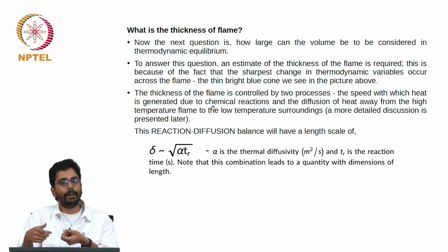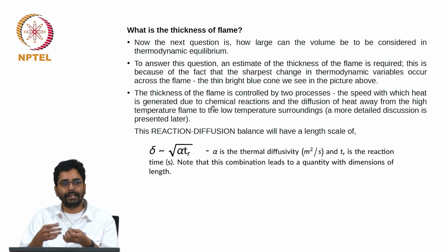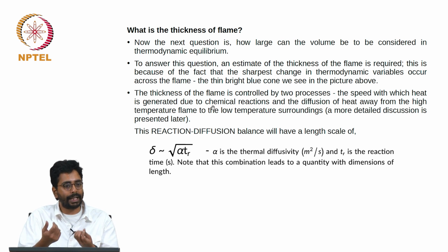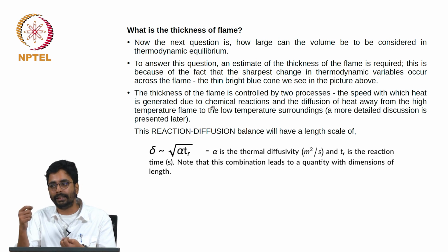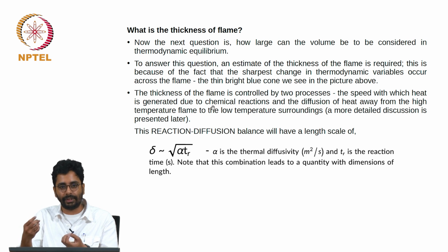time, but the reactants are continuously getting converted into products and heat is being generated, and unless the heat is removed from the reaction zone at the same rate, the temperature cannot remain steady. That the temperature remains steady means that heat is removed at the same rate that it is being generated, and this balance is what is maintaining the temperature profile.